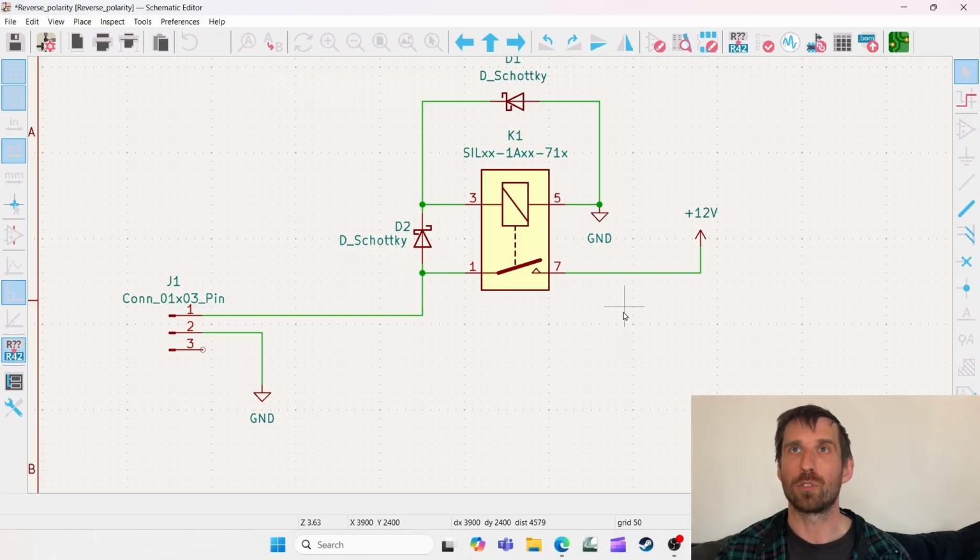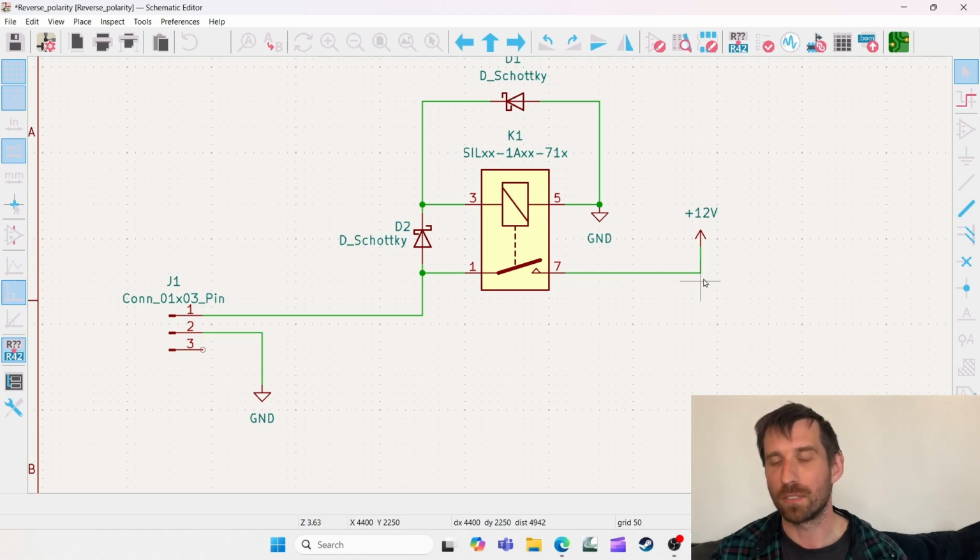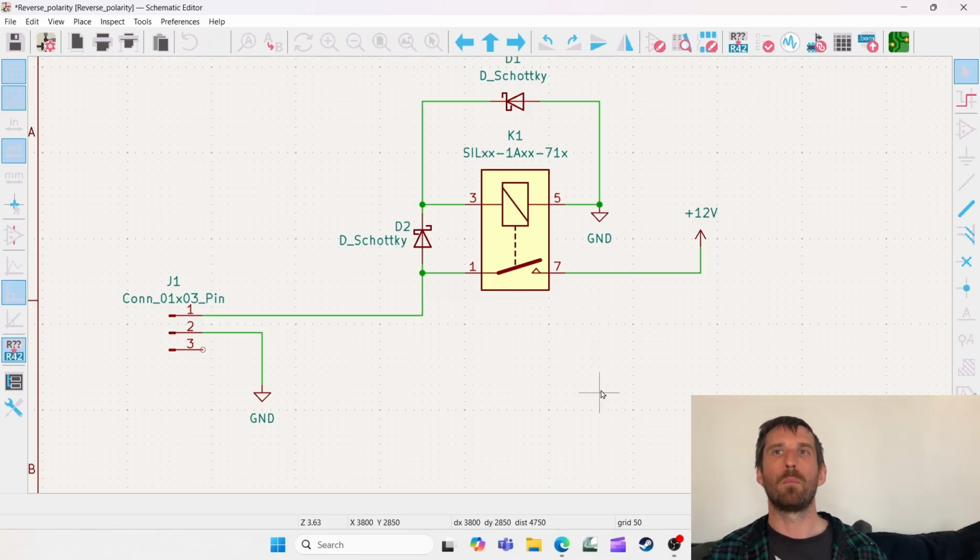And then at the initial turn on, there's probably peak current because of capacitive load, basically all the capacitors in the circuit. So it creates a brief period where your current is very high. So that wears out the contacts after a while. What the AI did not mention is that